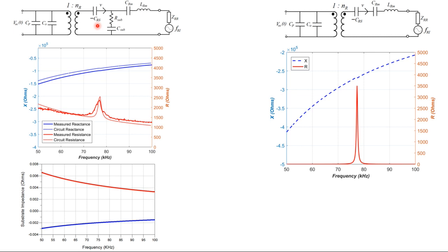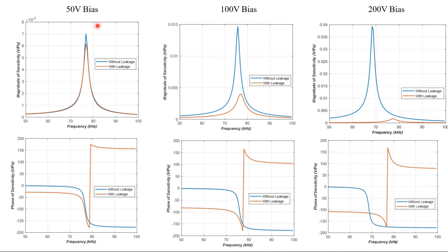When the membrane is biased very close to the substrate, you're going to compromise the sensitivity. The sensitivity is compromised even at very large coupling coefficients. So no need to bias the membrane very close to the substrate. You're already losing the CMUT receive sensitivity at large biasing.